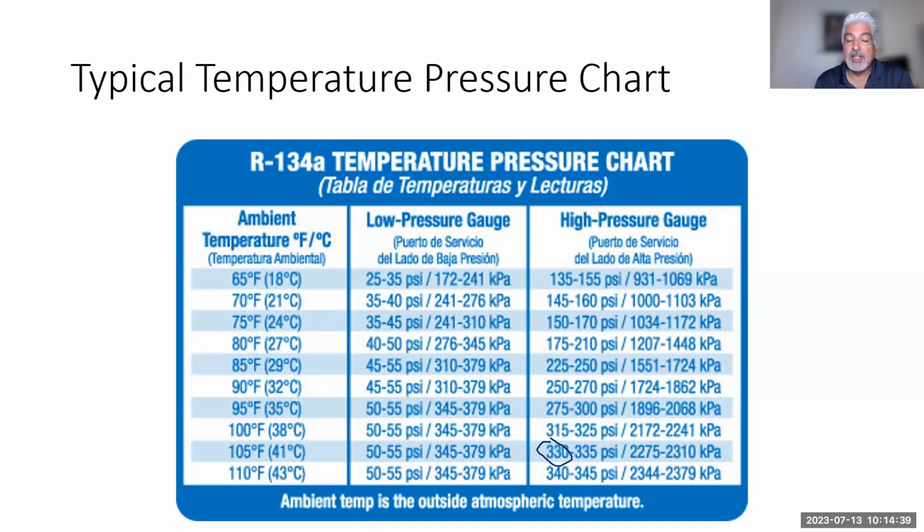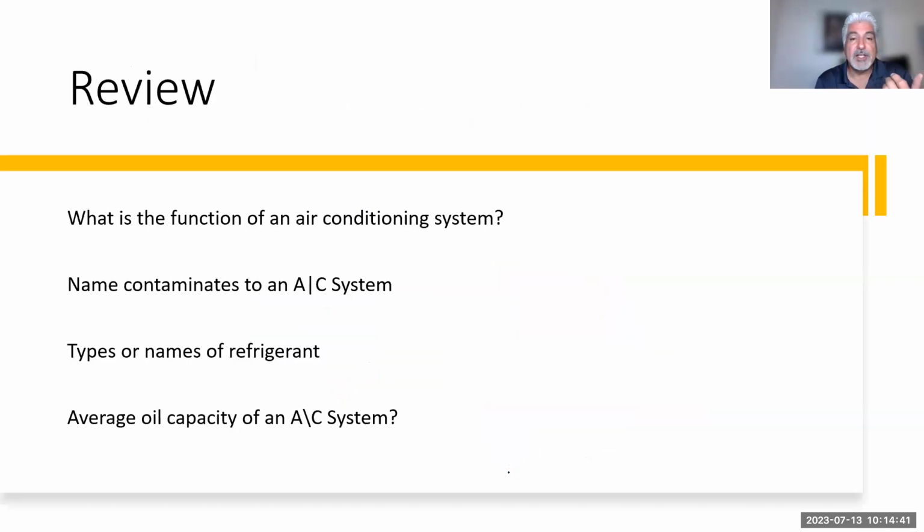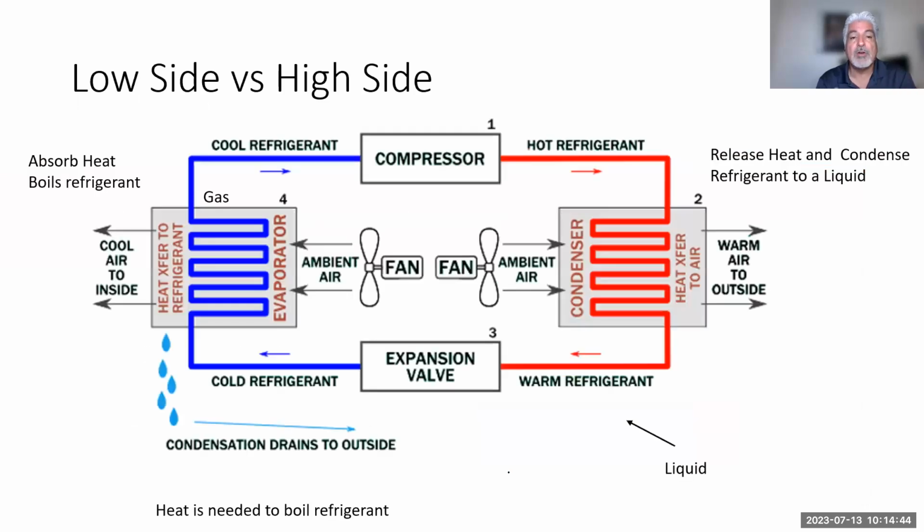Since we're on the subject of voltage drop testing, it is also a good idea to make sure that your blower motor, the fan assembly, is also getting full voltage as well. So if you're on high, please note, whether it's a relay or a module, the blower motors themselves also need full battery voltage to get full speed. So it's a good idea, if you can access it from the bottom or the outside, depending on the design, to do a voltage drop test across the blower fan to make sure that it's getting full voltage and full amperage at the high speeds. Because again, you're trying to ensure that there's no unwanted resistance.